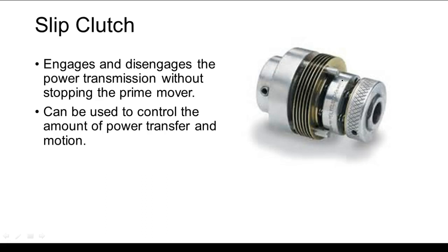So if you ever drive a straight shift, learning how to use that clutch is really important, because if you let the clutch all the way out, all odds are your engine's going to try to pick up all that torque instantly, right? You understand? Or you let it out slowly, and then you manage the torque transfer.